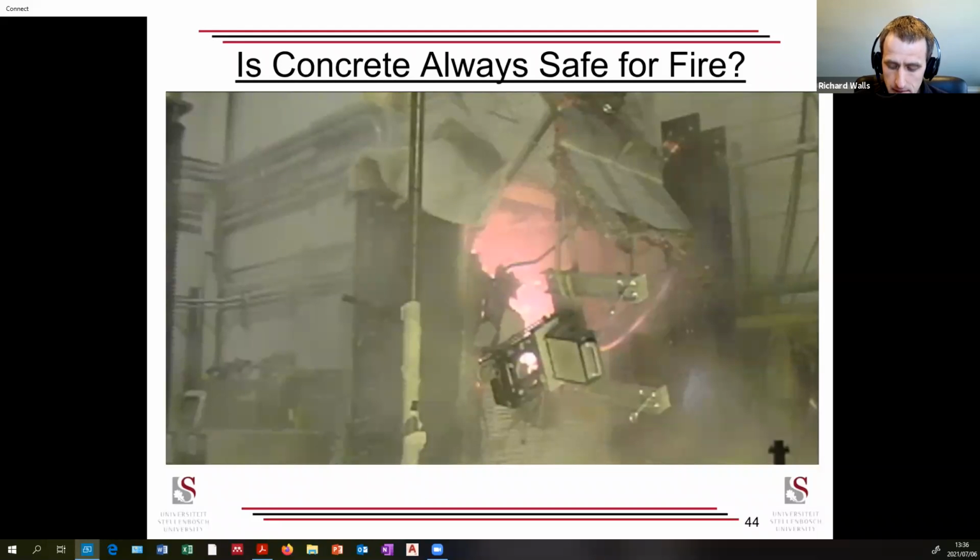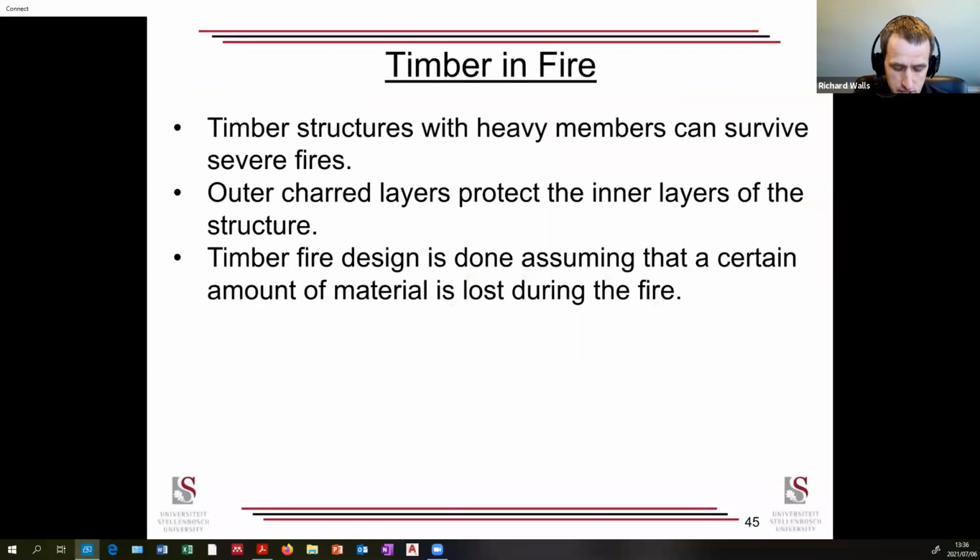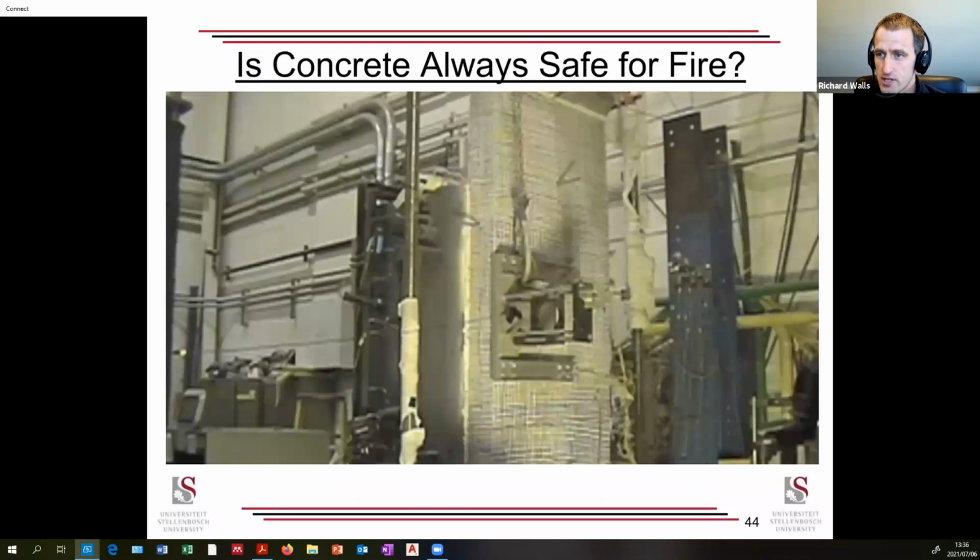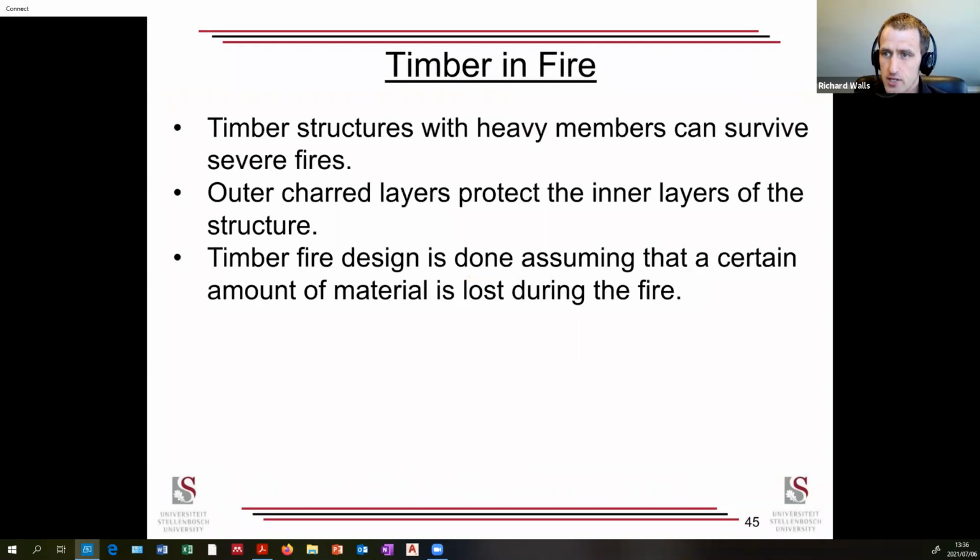And then also you have conditions where some materials do degrade. For instance, your post-tensioning, pre-stressing steels, your high tensile steels can permanently lose strength, so they can be a problem, so you have to look at them. And there are other areas you may have to look at. I'm just trying to give you a very brief overview of structural fire design at this stage.